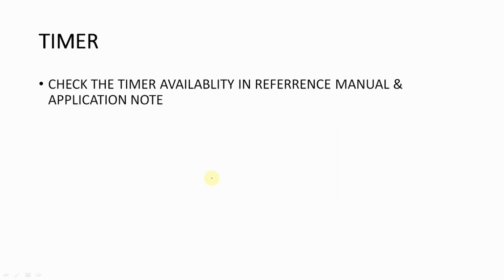For further clarity, you can refer to the user manual of the STM32F446RE microcontroller, or whichever microcontroller you are working on; look into the reference manual or user manual for the availability of timers in your microcontroller. As per the STM32F4 series microcontroller, timer 6 and timer 7 are basic timers. These details I have just derived from the reference manual. Basic timer means this timer is useful only for producing accurate time delays, or accurate time delays at every timer interrupt that occurs.